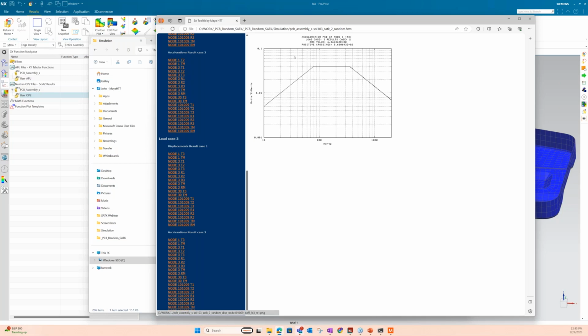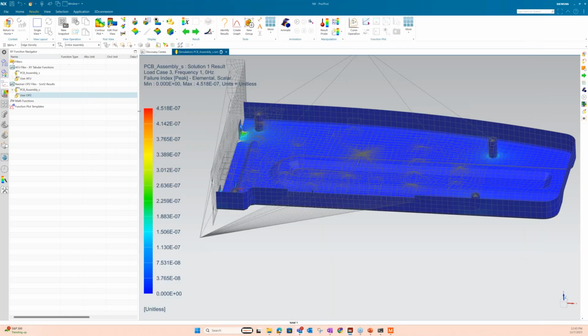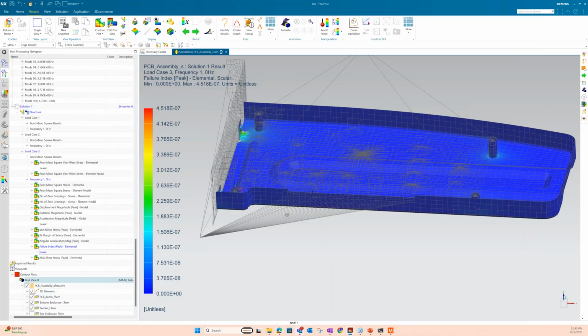I chose my base excitation node, and it's a quick check to see, okay, my PSD looks like what it should be. And then from there, you can say, I want to see displacements. What do my displacements look like on the different nodes in here? And you can look at the frequencies. Just a simple quick check. You can also plot them in here as well. And that's basically it. It's pretty fast, pretty easy.